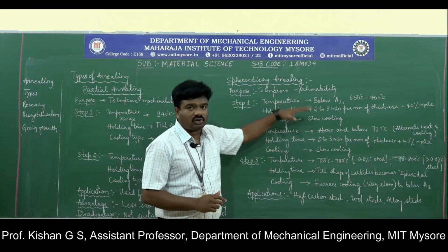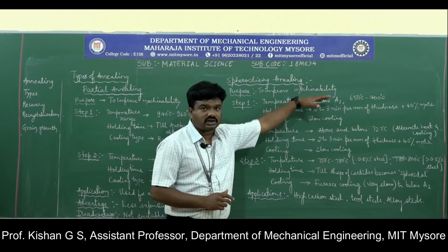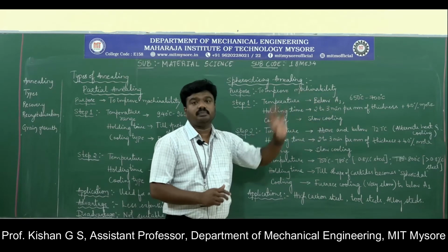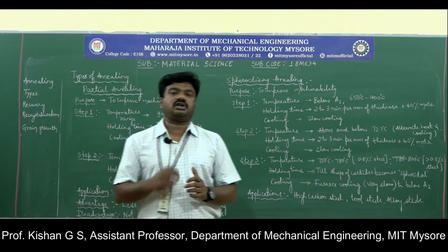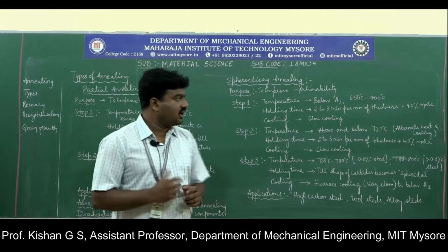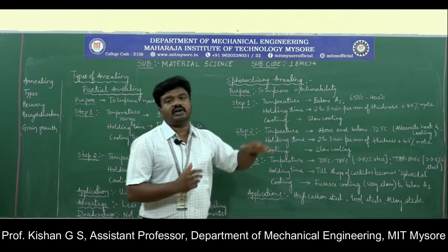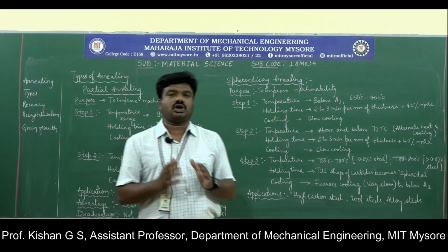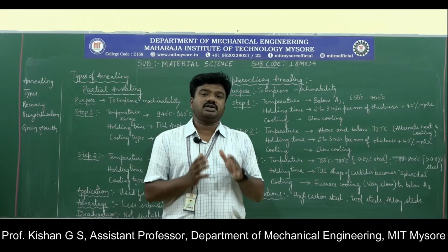Followed by you are going to hold the specimen at that temperature 2 to 3 minutes per millimeter of thickness and even 40% more duration. Followed by the cooling, which is a very slow cooling process. So it is normal cooling which is accountable at stage 1.